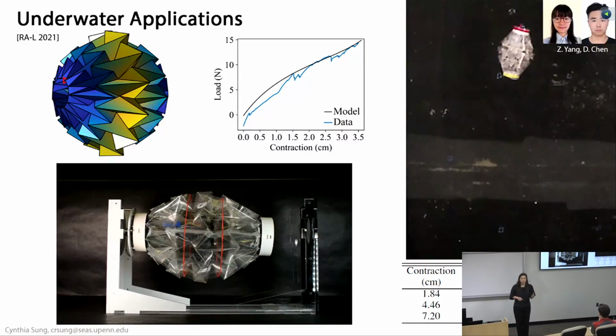Could you make it so that this operates like a squid, that I have a fold-up device that has a vacuum, and then in addition to the expansion, I can actually push the water back? Yeah, in this case, that was the main idea, actually, that we were inspired by squids. What you're seeing in this video here is that when we compress the ball, it expands in volume, so that sucks the water in. Okay. And then when we release, the ball very quickly contracts, and that creates the jet that pushes the robot, as in the figure. Okay, yeah. Okay, thank you. Other questions?